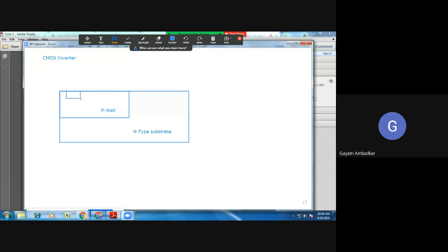So we have one n-type block here, another n-type block here, right? And above this we have SiO2 layer. SiO2 layer will be present throughout, okay? But to take the connection from here, we will etch it, and again we will form the SiO2 layer. But now for understanding, I am showing only above the gate. And this is SiO2 layer, and above SiO2 layer, a gate is deposited.